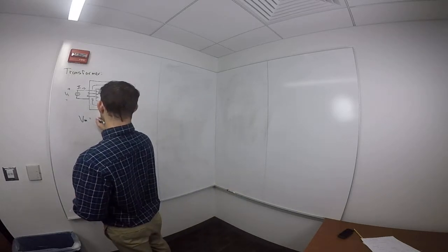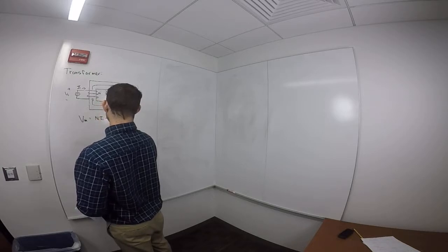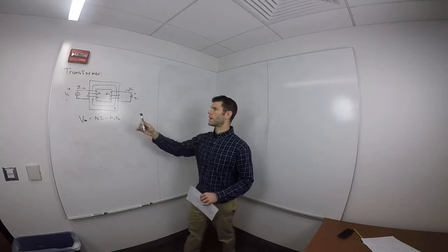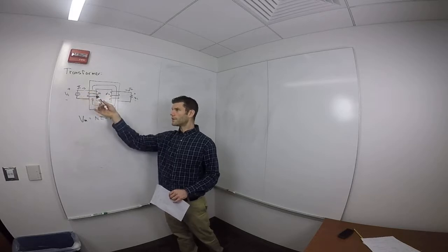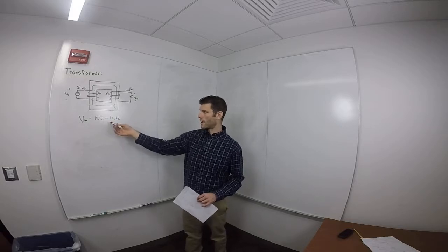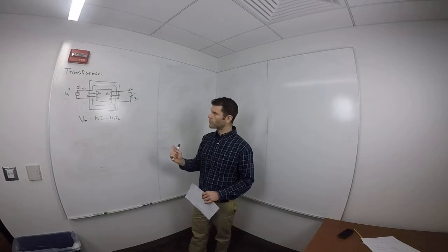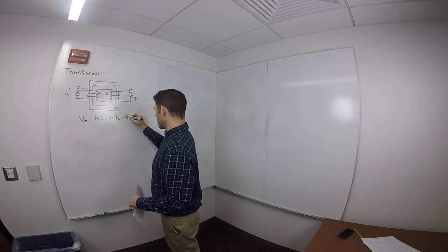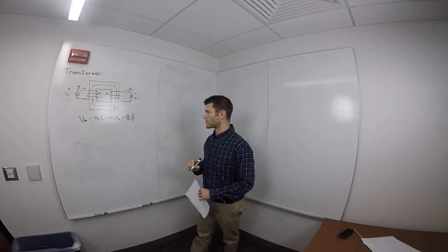So we would say N1 I1 minus N2 I2. And the reason why we say minus is because you can see that in the way we denote it here, we have the current I1 flowing into the solenoid, but current I2 is flowing out of the solenoid. So this is just telling you the directions, okay? Well, the difference between those two, basically using Ohm's law for magnetic circuits, is going to be equal to the reluctance of that core times the flux which flows through it.